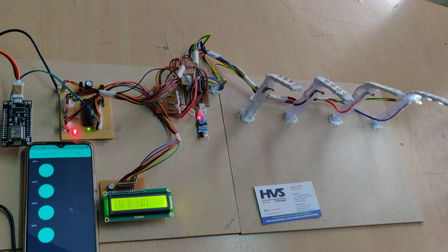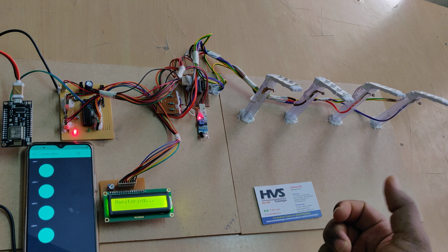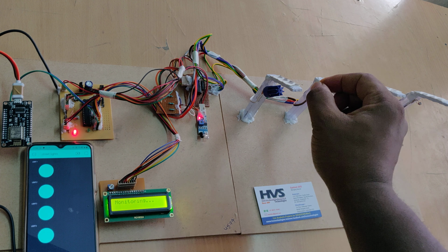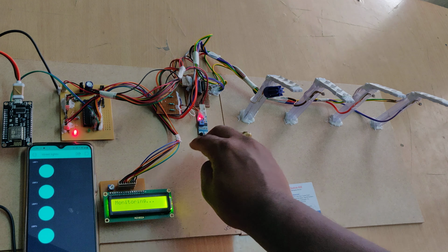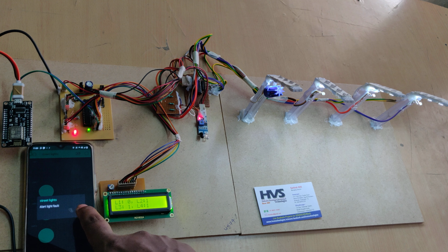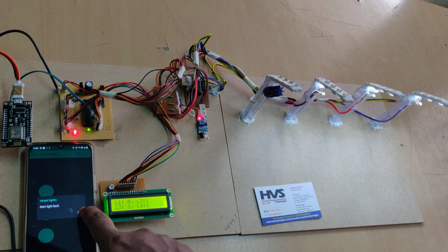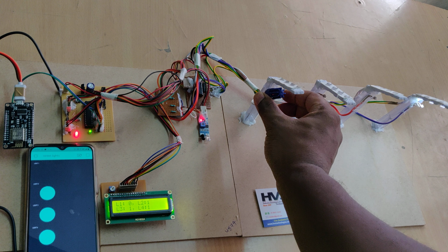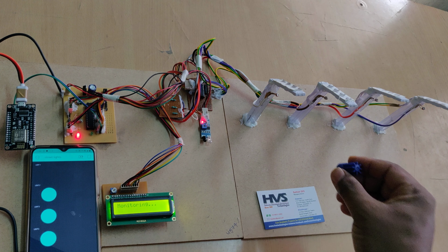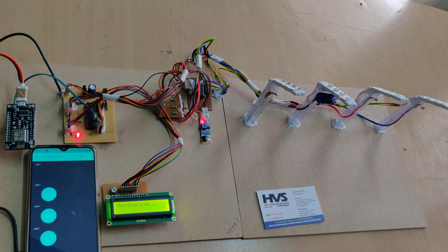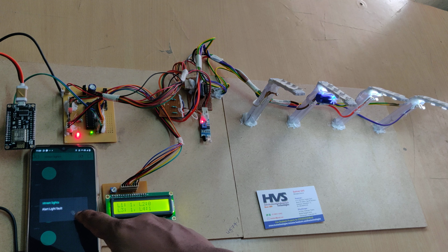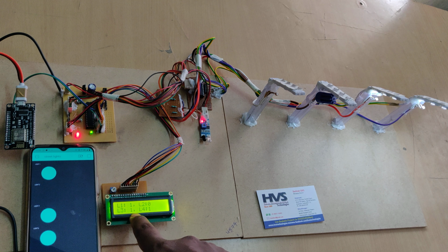For every 3 seconds, the next street light stays on while the previous street light switches off. If we cover one LDR, we are indicating to the system that this particular light is not working. Then you can see here the alert, light fault, and also L1 is 0 and L2, L3, L4 are 1, 1. The same thing for each and every light will be detected here continuously. Now light 1 is on and light 2 is in the off state, and here also we can see the same thing.